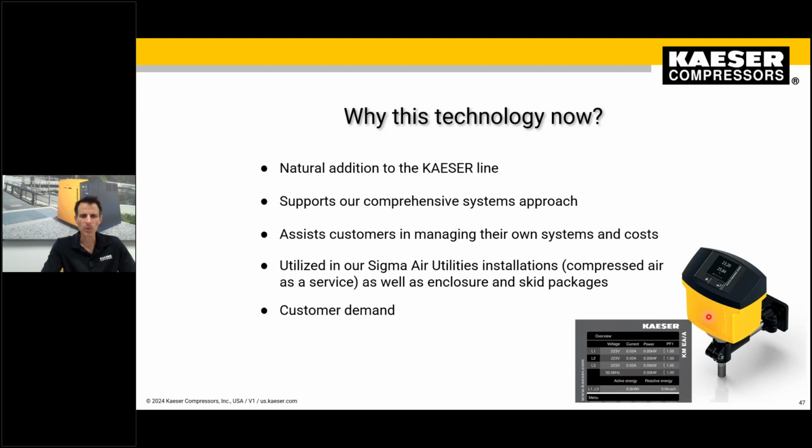What we want to provide is what customers need, not necessarily what customers want. And those are always hard conversations to have without data. With data, obviously, it's a lot easier to say, okay, maybe your budget is 200 horsepower and we want to split that between two 100 horsepower compressors, whereas most customers might be more inclined toward one 200 horsepower VFD. And if we have the data, maybe that shows that we really only need 100 horsepower worth of compressed